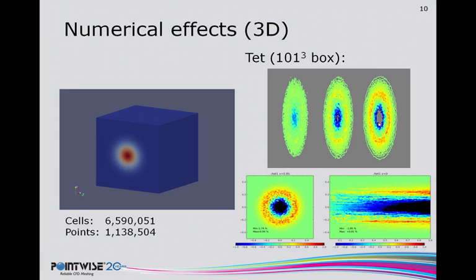The idea here is not that a tetrahedral grid will always introduce this much error, but rather, if you can avoid using tetrahedral grids in regions with very sharp gradients, such as a boundary layer, you're going to be able to achieve a more accurate CFD result, regardless of the algorithm that you're using. In fact, this is one of the primary motivations for the T-Rex feature in Pointwise, which allows you to create these high-quality prismatic boundary layers, or now with this new feature, hexahedral boundary layer elements, to help really resolve your boundary layer and those regions of sharp gradients while maintaining the flexibility of this unstructured tetrahedral far field.